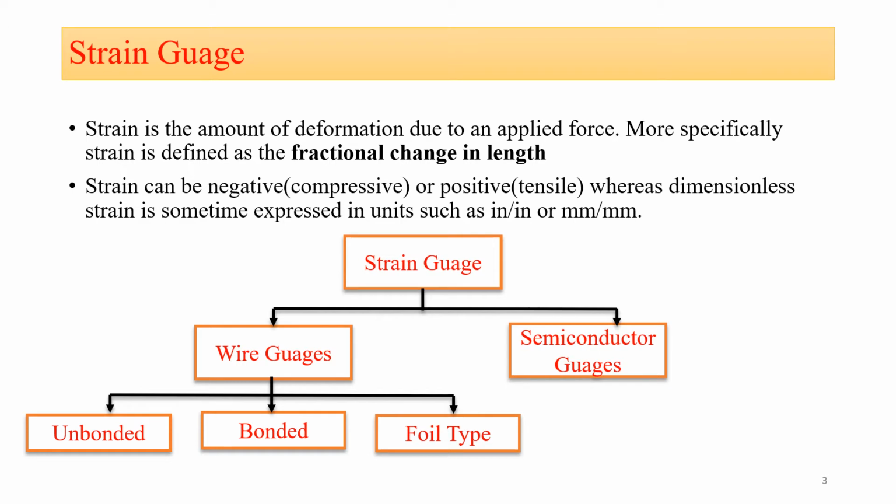Also, a strain gauge is a passive type of sensor, and it is also a resistive transducer which converts the mechanical elongation and compression into a proportional resistance change. This change in resistance takes place due to the variation in the length and the cross sectional area of the gauge wire when the external force is applied on it, and the variation in the resistance is converted into the variation in voltage by connecting the strain gauge in a Wheatstone bridge.